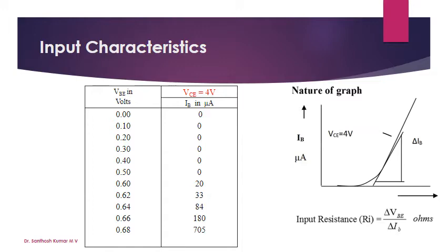The base current does not start initially; it starts from one particular voltage onwards. With the first reading, we got readings when the voltage reached 0.6 volts. Upon that the current increases steeply. Before that, no current is measured.